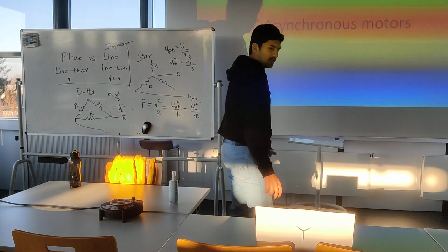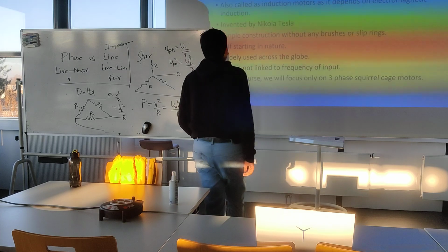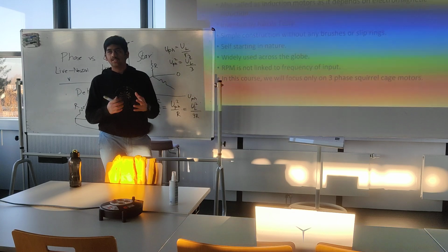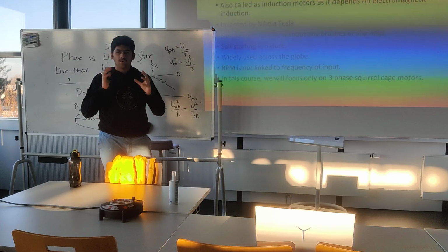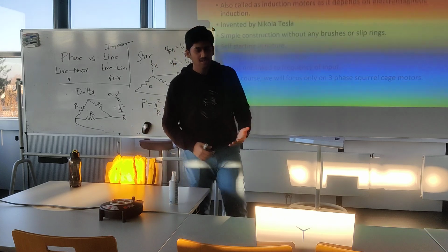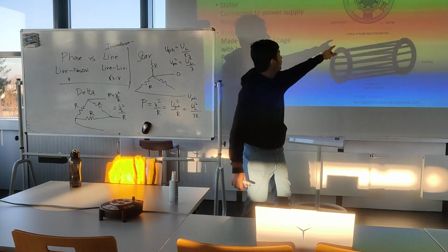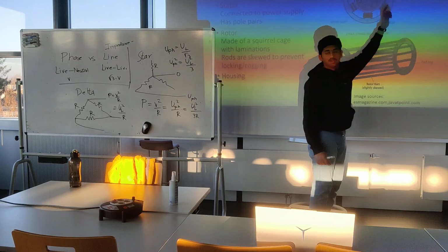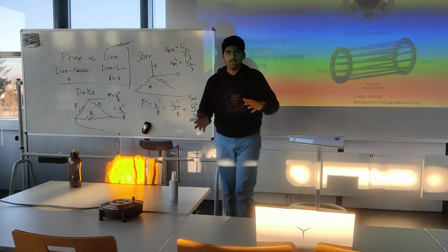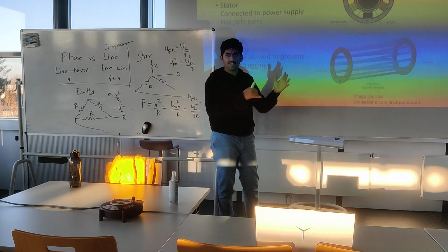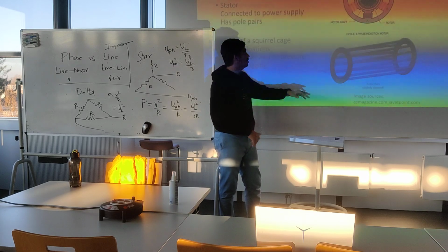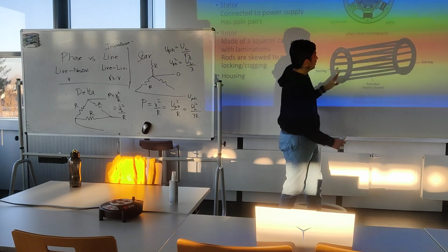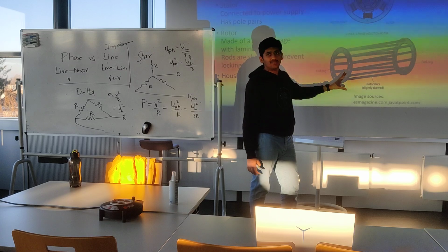So now let's start asynchronous motors. They are also called induction motors, because here we don't have any separate field generating coils. We just have one stator coil that's going to generate a rotating field. So we have these stator coils, they are going to generate fields, and the field vector is going to rotate because the three phasors from the three-phase AC are rotating.